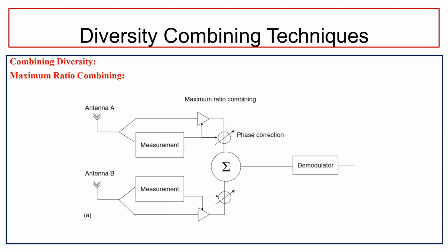Because of this, the advantage is that an acceptable SNR can be obtained with the best statistical detection of fading. But the drawback is the high cost. Each and every branch has to be weighted, which requires faster processing, and all branches should be in phase, so it requires more concern.